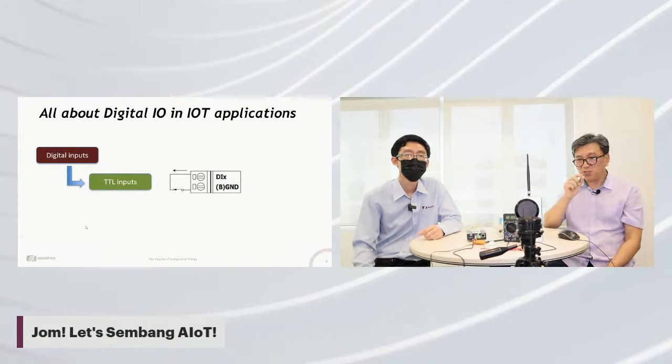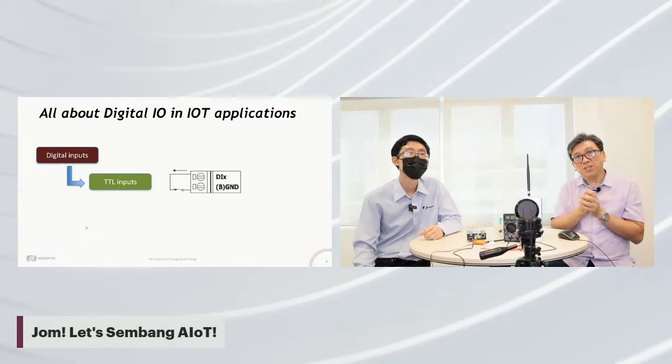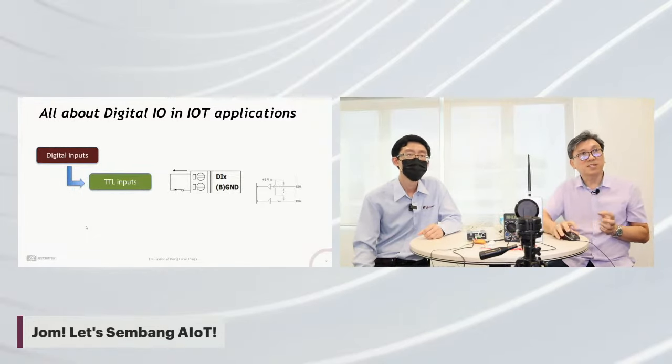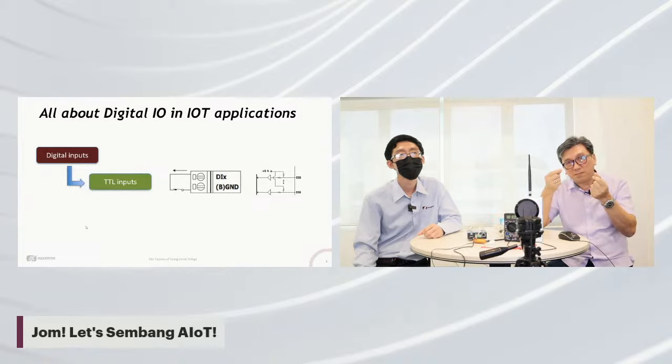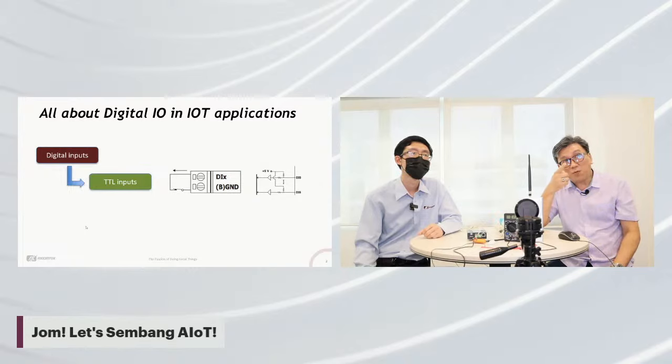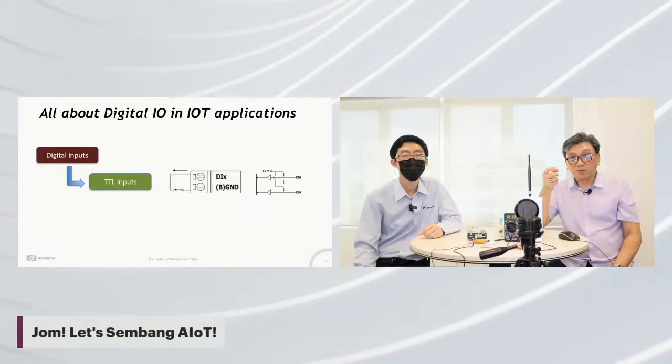There is no special treatment to it. Basically you can see in the circuitry, in the electronics, it's a combination of a semiconductor input, just an IC with a resistor put across. For example, in this case you can see a 5 volt, actually a pull-up 5 volts, that allows you to give a dry contact to it.